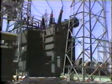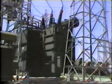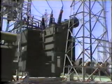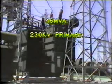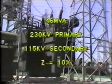But how do we know, or how can we find out, the value of impedance for each item of equipment? Well, quite simply, it's usually marked on the schematic and also on the nameplate of the equipment itself. A typical example is this transformer. The nameplate shows that it's rated at 46 MVA, 230 kV primary, 115 kV secondary. The impedance is indicated as 10%.